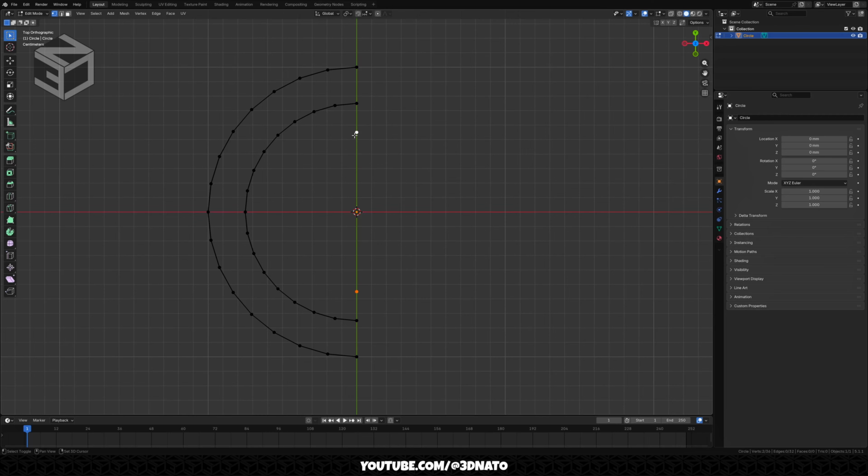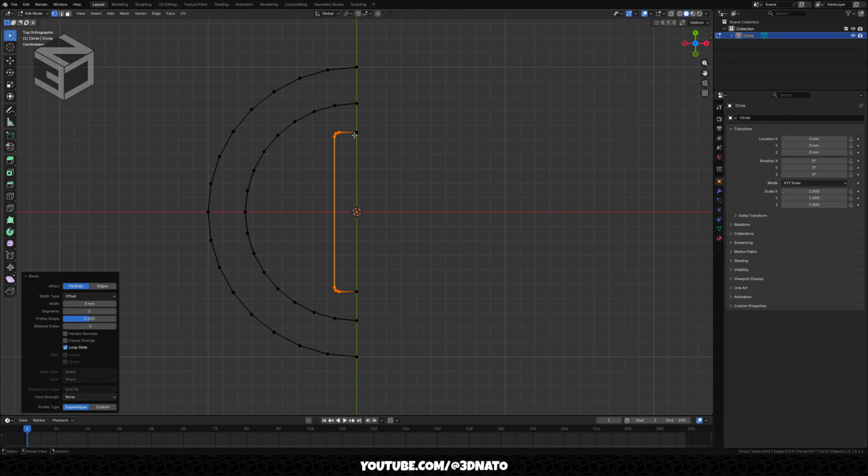Select both vertices, then press E to extrude, X to lock the axis, type -15 and hit Enter. Now press F to create a new edge, then press Shift plus Ctrl plus B for vertex bevel. Type 3 for a 3mm bevel, press numpad plus to increase segments to 2 and hit Enter.